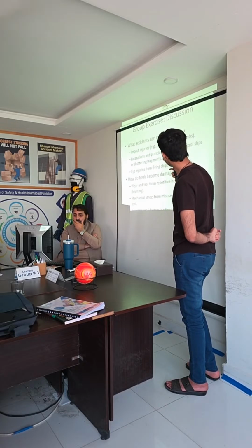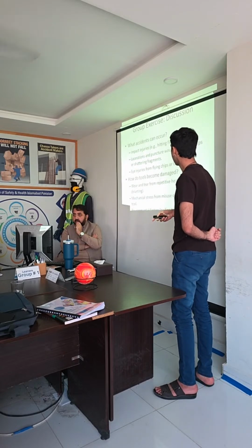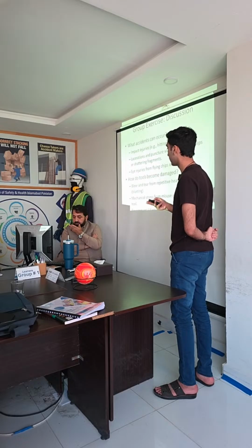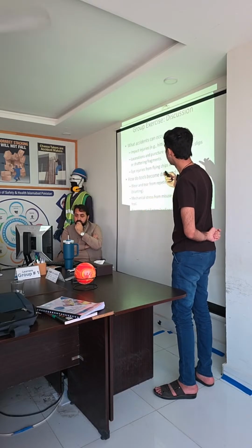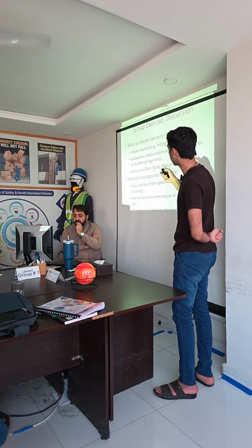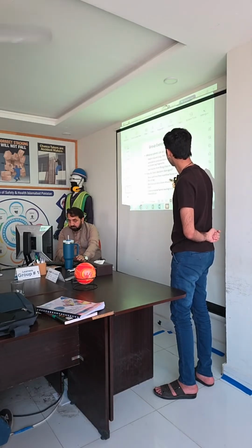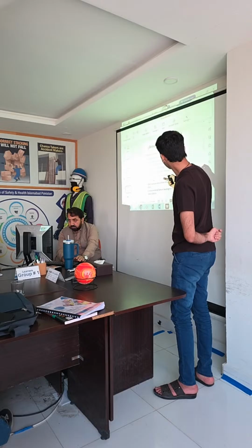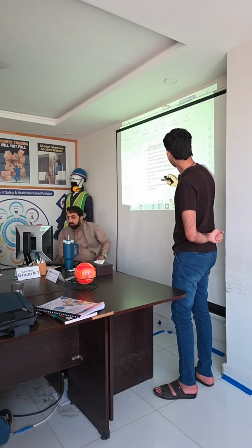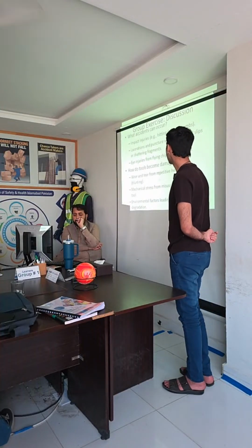So there was a group exercise in this too. What accidents can occur? Like impact injuries, like hitting fingers or thumbs, or if the hammer slips off from your hand, it can hurt your feet as well or anybody else. Then there's lacerations and puncture wounds from tool slips or shattering fragments. Then there's eye injuries from flying chips or tool debris.